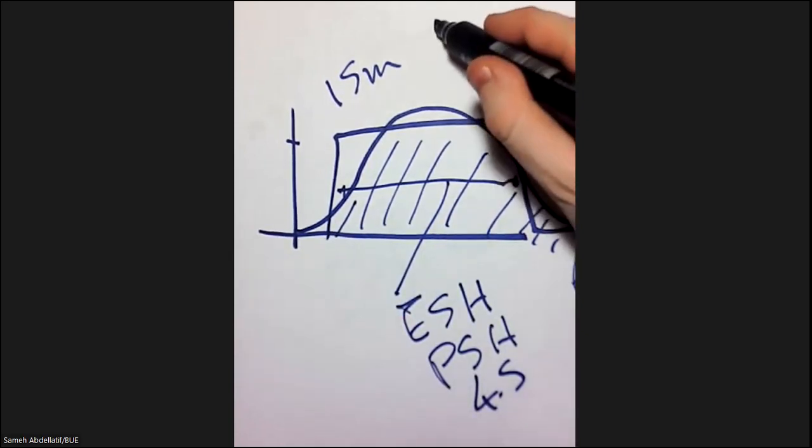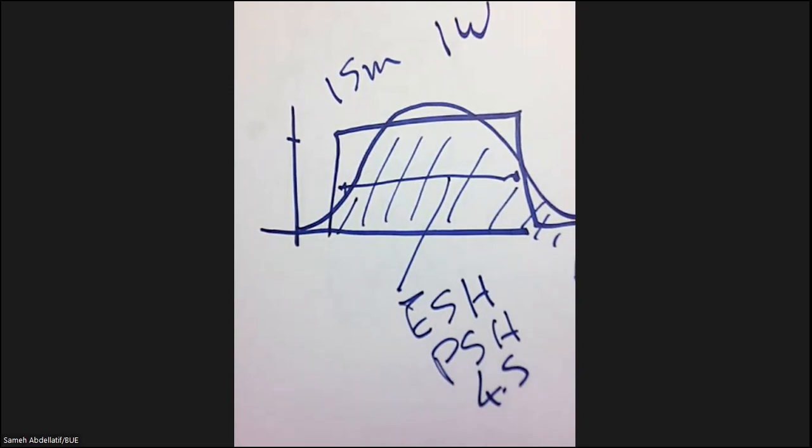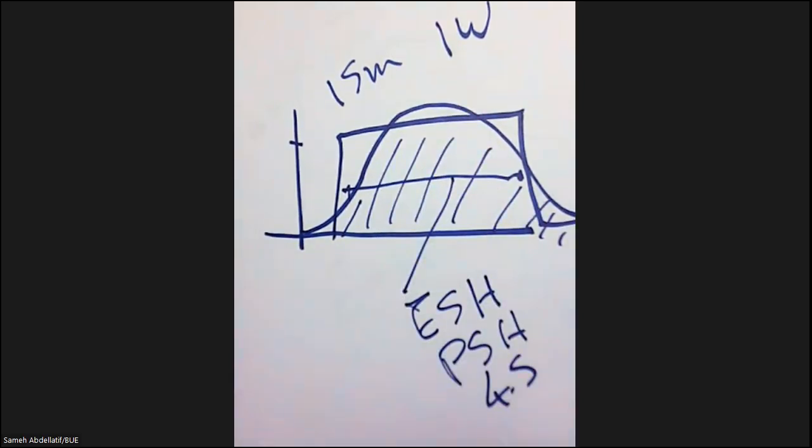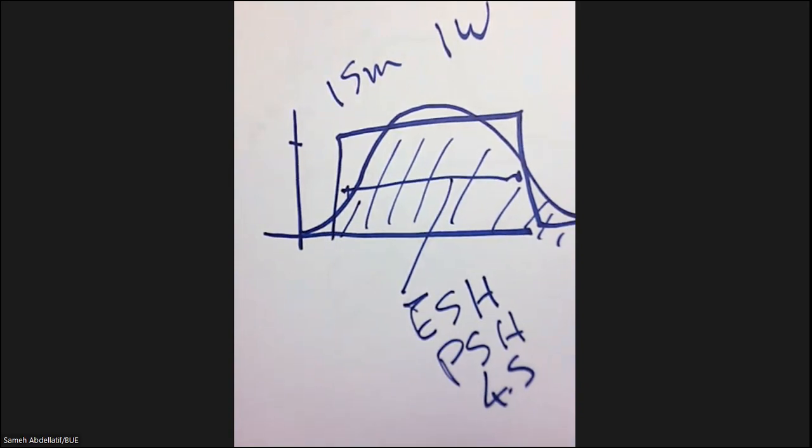And your PV module is 1 watt. That means that simply, if you fix this 1 watt PV module to the sun per day in autumn, it will produce 4.5 times 1, which is 4.5 watt hour per day. So you estimate the energy of this PV in just one step calculation by using this equivalent sun hour or peak sun hour model.